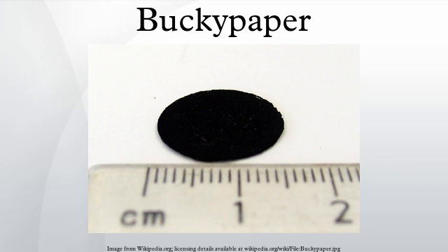The dimensions can be controlled through the size of the syringe housing and through the mass of carbon nanotubes added. Their thicknesses are typically much larger than surfactant-cast Buckypaper and have been synthesized from 120 µm up to 650 µm. Whilst no nomenclature system exists to govern thicknesses for samples to be classified as paper, samples with thicknesses greater than 500 µm are referred to as buckydiscs. The frit compression method allows rapid casting of Buckypaper and buckydiscs, with recovery of the casting solvent and control over the 2D and 3D geometry.